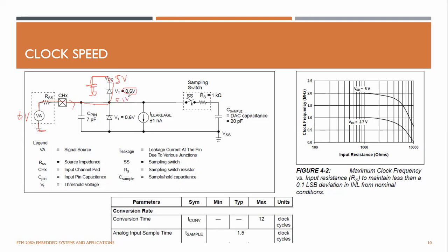And 5.6 volt, and the rest of the 4 volt will be dropped across this impedance, together with the series source impedance and the PCB traces and this pin's internal impedance. So that's how it is safe. No matter whatever voltage you apply, you can apply up to 7 volt as the absolute maximum rating. This voltage at this pin will be kept at VCC, VDD plus 0.6.